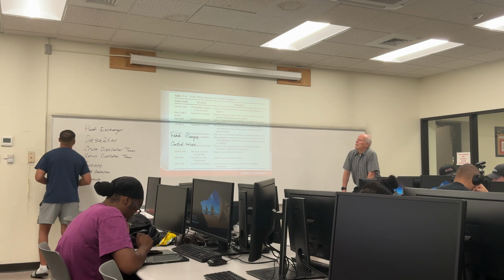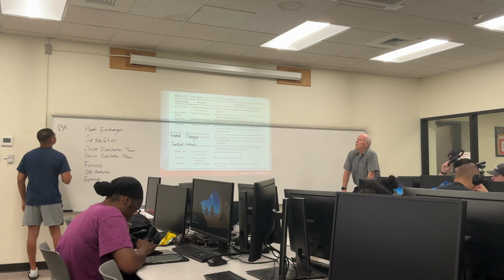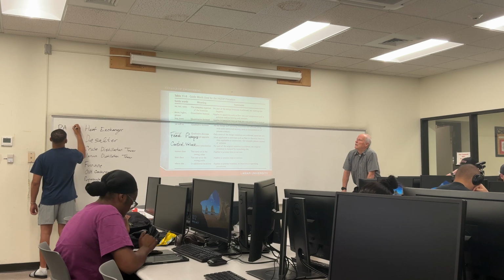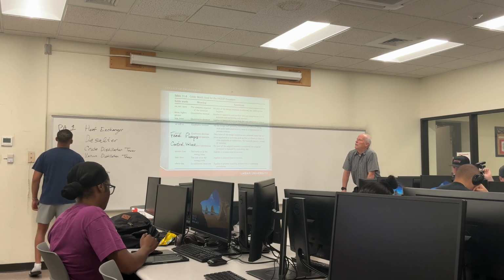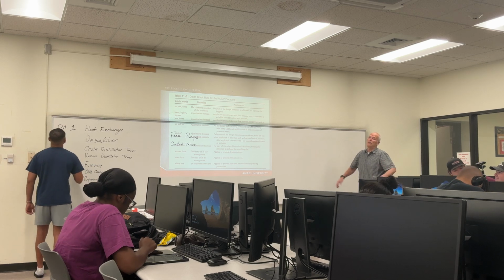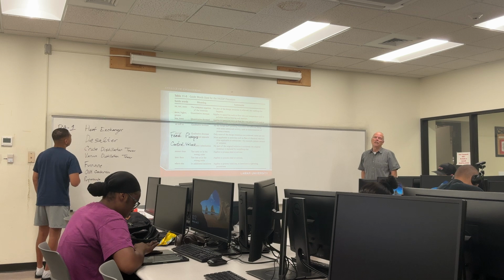You have three different pump arounds, don't you? Just pump around 1, 2, or 3. Okay, we'll call one the one highest up in the tower, so that's the coolest pump around. What is the design intent of that heat exchanger?